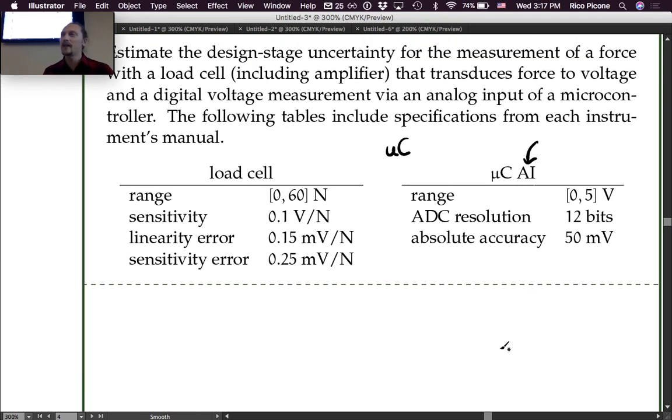So this setup, as was pointed out, is not perfect as it is, and we would probably need to do some things to make it a little bit better. We should probably divide down that with a voltage divider, in which case it would be totally fine. We would then go for 0 to 5 volts with our load, but we would have to multiply the voltage that we get by this voltage divider factor. We should undivide it, right? Multiply it back up so that it is the correct value. So we just have to be careful.